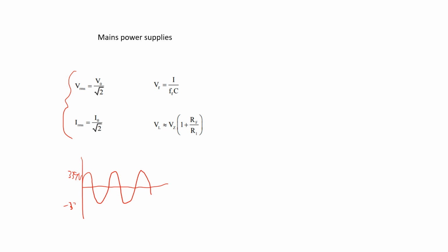But if you're to take the average value of that, it's called the RMS value, and it's about 70%, funnily enough, it's always 70%, isn't it? That voltage there would be about 230 volts, between 230 and 240 in the UK. Fluctuates at different times of the day, but that's the RMS, the root mean squared voltage. Okay.